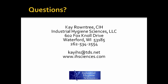I think you start out looking for your worst case examples, and if you're under the exposure limits on your worst case, and you feel that you have good reason to believe that is your worst case, I think you're standing good that you don't have an issue with hex chrome. Obviously, if you're over the PEL or over the action level, that's a different story.